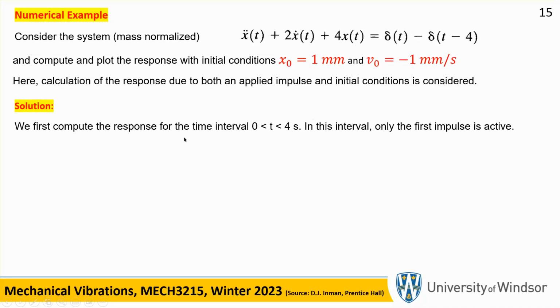So essentially, it's the same problem as before. If you look at the equation here, this immediately tells you what the mass is. m is equal to 1. But think about it as m equal to 1, and this is 2 xi omega n, and this is omega n squared. As long as the coefficient in front of x double dot is 1, this is called the standard equation, the mother of all equations.